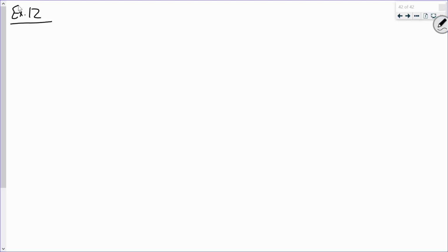All right. So let's get into this example. A few things we need right off the bat are some material values. What can you tell me about the concrete? We know it's 4 KSI, but what else? Normal weight. So for the concrete, we know that f'c is 4 KSI, lambda equals 1, and gamma is going to be 0.15 kips per cubic foot.